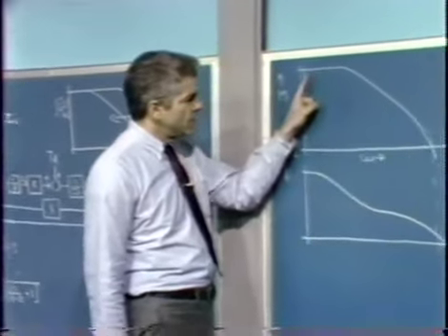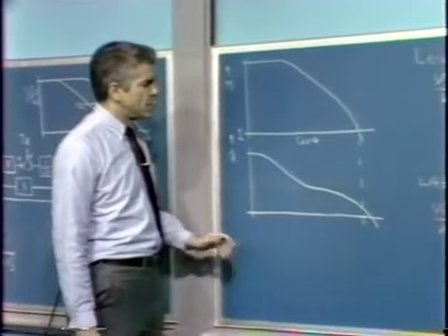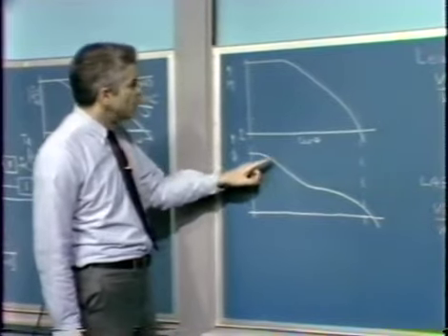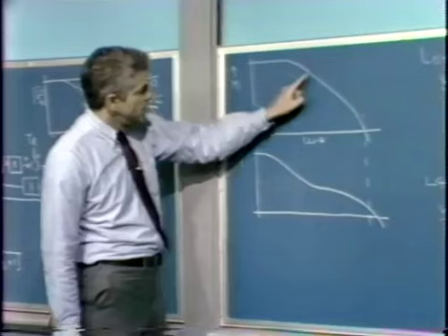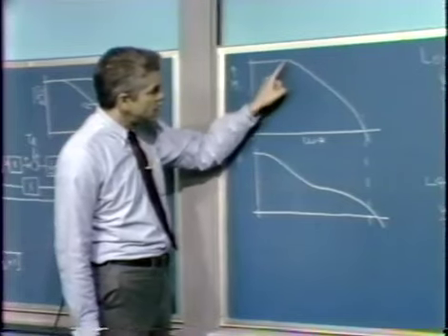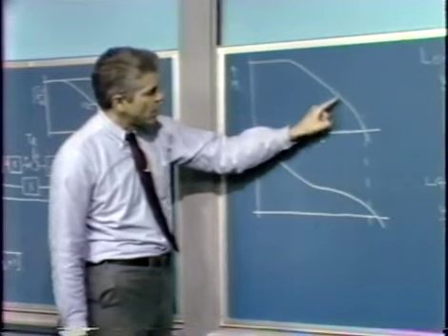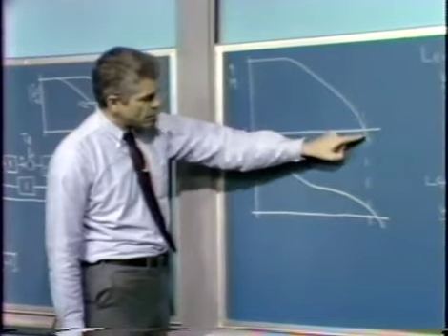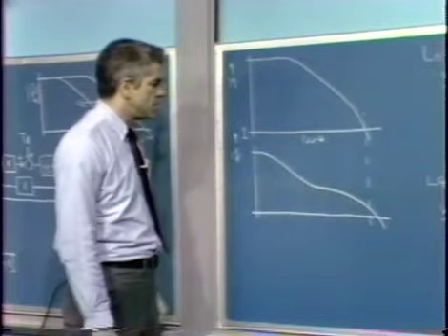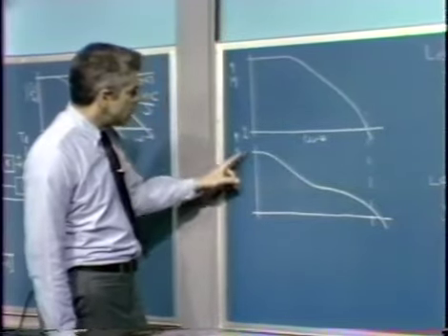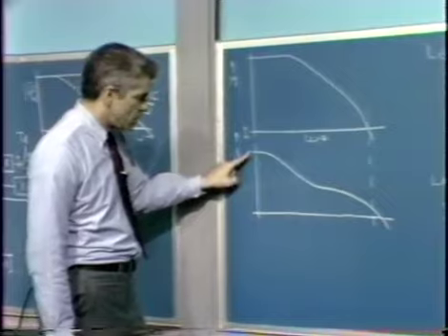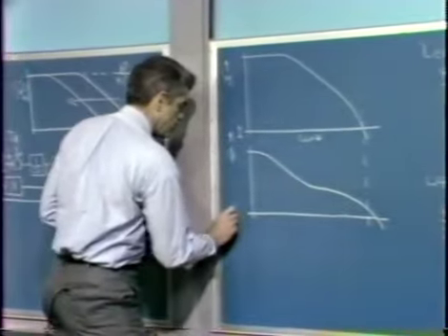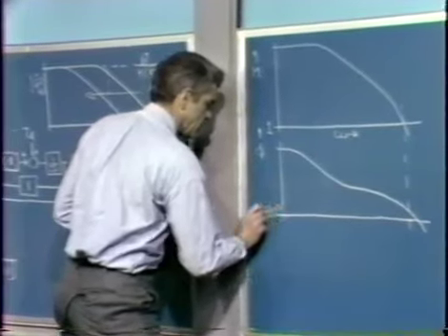Here again I've shown a Bode plot for the AF product for some hypothetical feedback system. This time I've showed a stable one. The magnitude is flat at DC, possibly a single pole roll-off in this region, and then some higher order poles or additional dynamics at higher frequencies. An associated angle might be one that was near 0 degrees at low frequencies. Here's the minus 180 degree point.